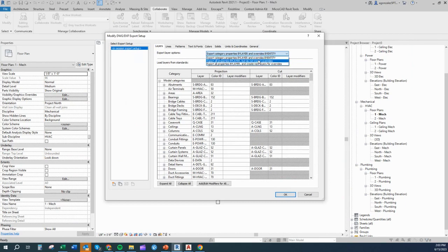The second one, view-specific graphics overrides will be ignored in the CAD application. In the exported file, Revit elements will reside on the same CAD layer as other entities in the same Revit category. By forcing all entities to display the visual properties defined by the layer, the option results in a lower number of layers and provides by-layer control over the exported DWG or DXF file.